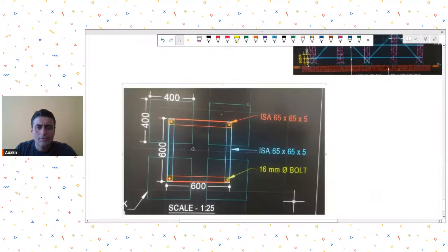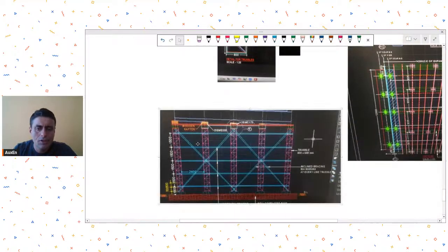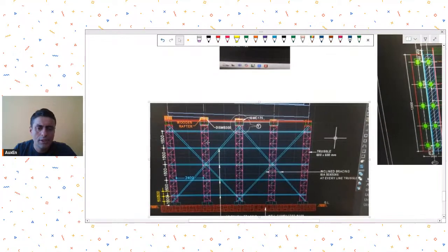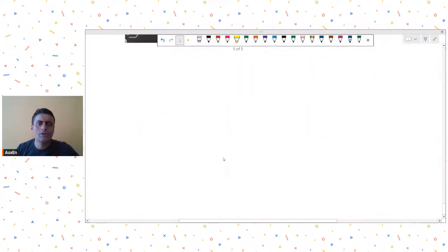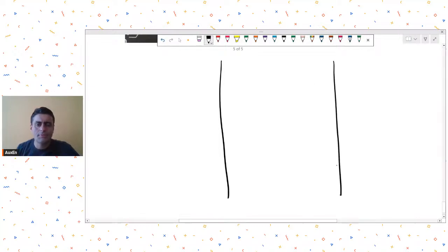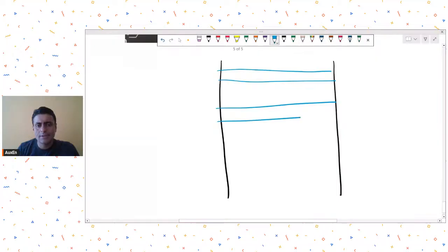So how this arrangement typically looks, let me try to show you over here. So typically there will be a bridge deck, okay? Let's say this is your bridge deck in plan view. This is where the mass concrete of your bridge deck is going to be poured. So typically you will have a girder arrangement, one level of girders at certain distances.